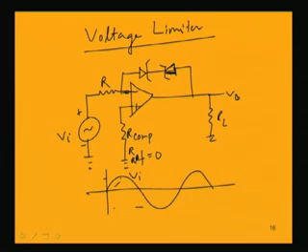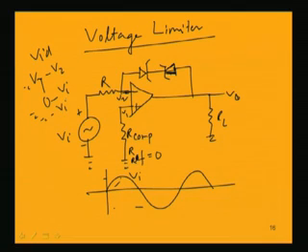So, the comparison will be giving an output voltage V saturation at V naught, and that will be negative V saturation, because VID is V1 minus V2, and that is equal to 0 minus Vi. So, that is a minus Vi. So, we are getting here a negative output voltage which is magnified by this op amp gain. So, if we consider V naught, for this portion we will be getting a negative. But then what will be this voltage?